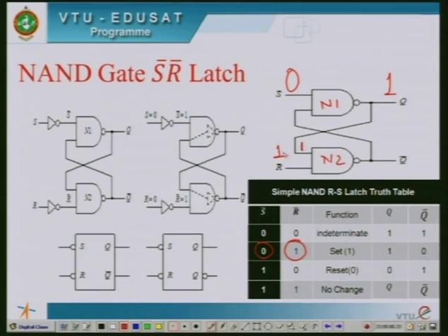So, for the second gate, both inputs are logic high. 1 and 1 is 1, NOT of that is 0. So, output Q bar will come to low state, and Q is in high state. This is called the set condition because Q output is logic high and Q bar output is 0. Output Q is what we are interested in, it is in set state. So, we call this the set state when Q becomes logic 1. This is how it works.